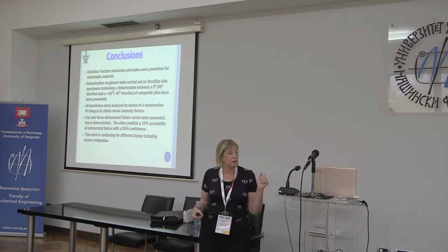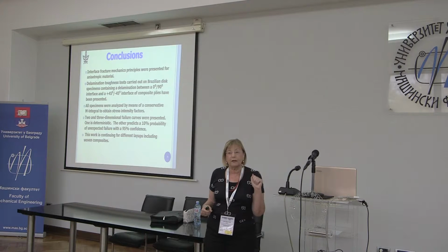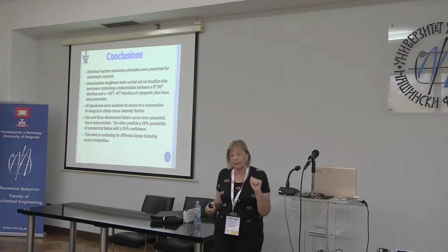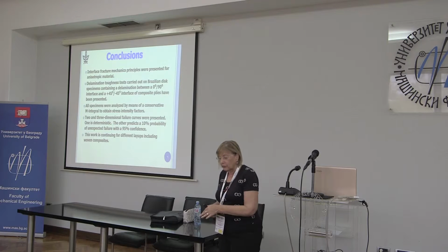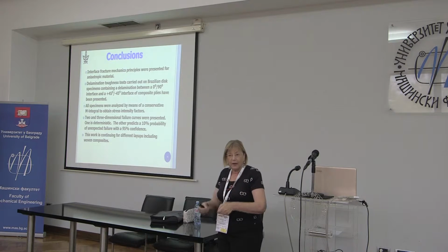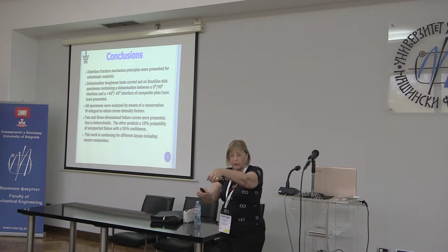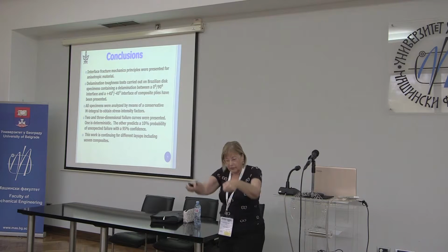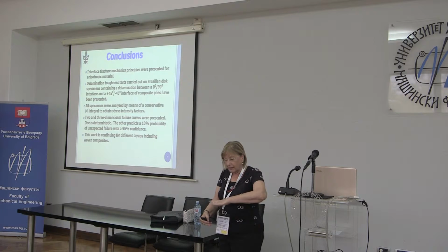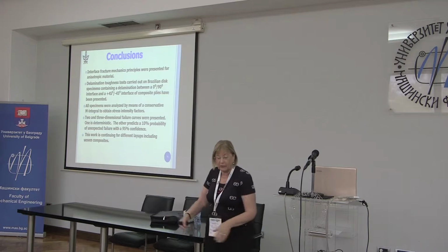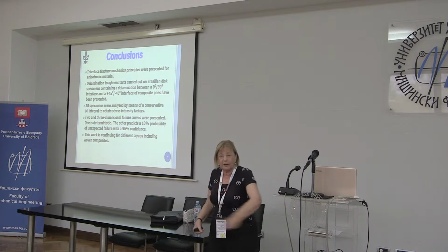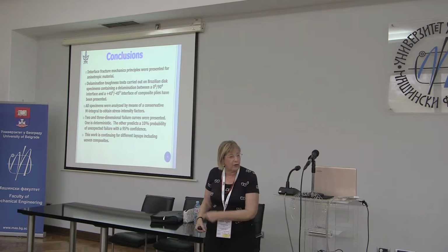Now, my student will talk about something called a wet layup. In a wet layup, they have like a woven material, so you know it's woven, and they're called tows or yarn. You put it down, and you have the yarn in, let's say, the 0-90 direction, and now somebody comes and puts epoxy on with a brush.